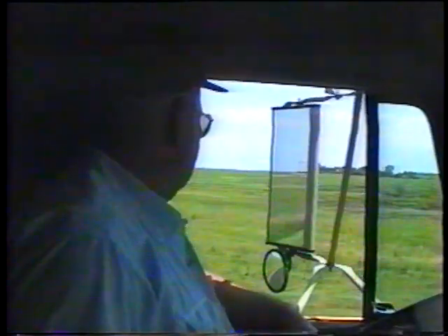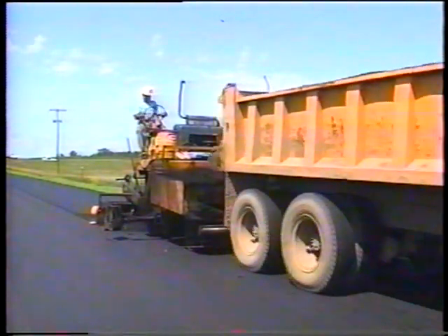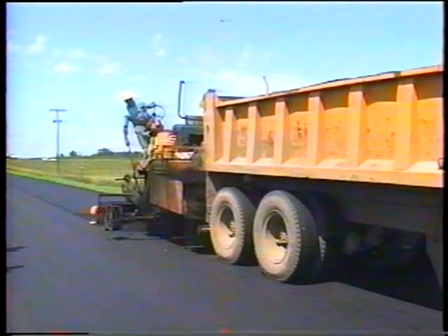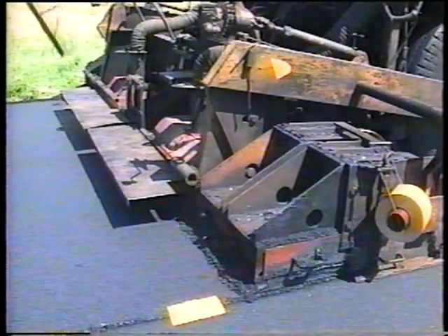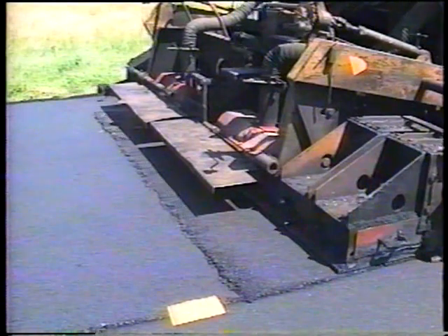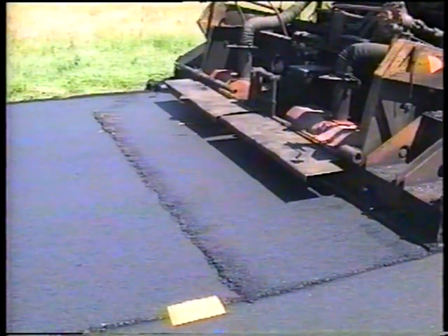This can put a lot of pressure on drivers to speed things up, which often leads to another consequence: trucks bumping the paver. The result, besides an upset whiplash victim, is that the truck knocks the screed back into the mat, creating a crease. A problem that's hard to fix, but simple to avoid with a little effort on the driver's part.